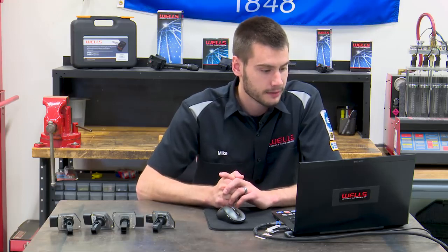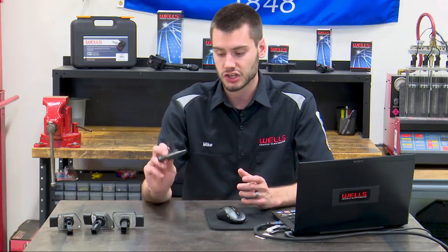Bax Rock 2 came on, a lot of comments from you. That's really awesome to see, I'm glad. But you were talking about checking voltage on the mass airflow. I think by the time we got to the end of the class, you realized that the GM mass airflow sensor we were working with does not output voltage, it outputs a frequency.